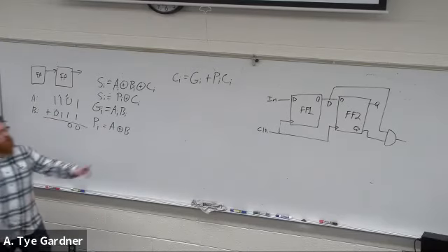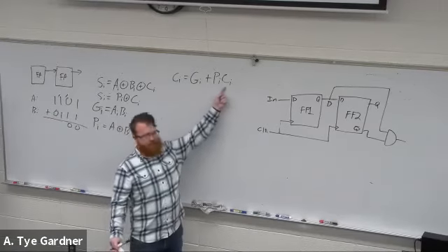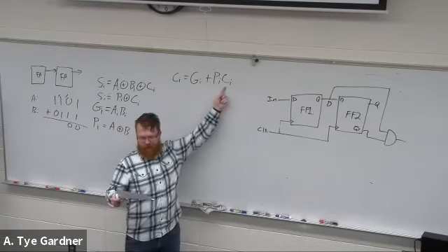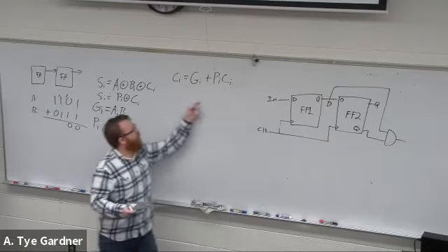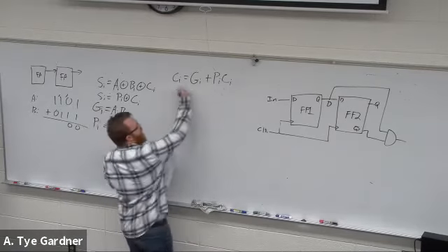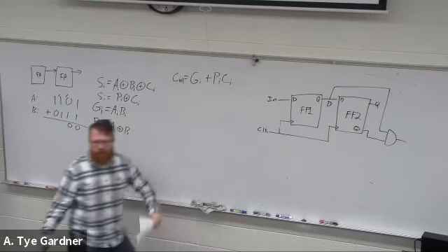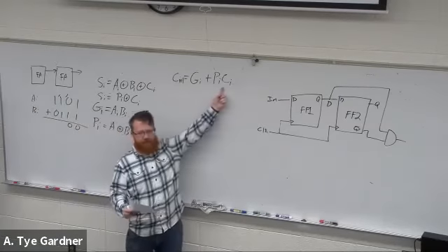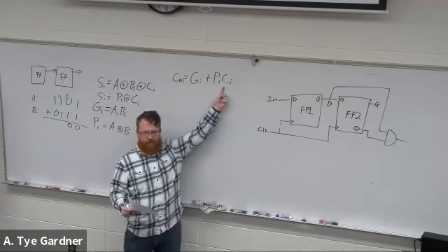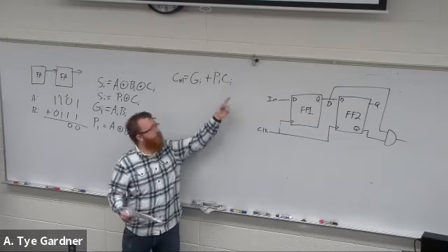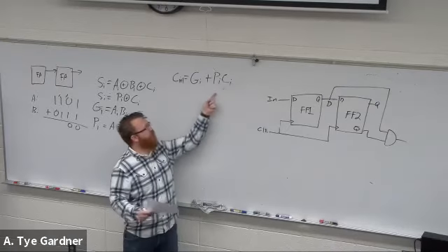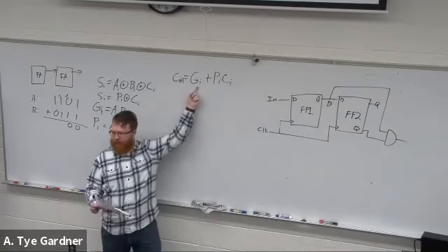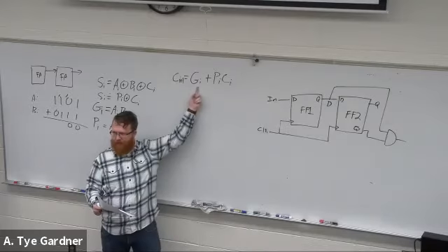Right? So if it's possible to propagate and there's a carry in, we're going to assert the carry. Sorry, this is I plus 1. So the next carry is dependent on the previous carry. Right? Fortunately, in the first one, there can't be a carry, so it's just, did I generate one? So the first one's expression is super easy.